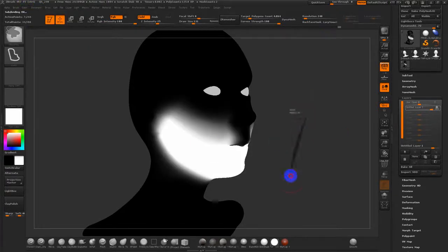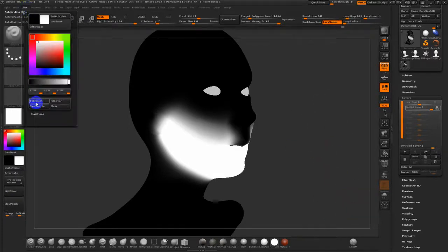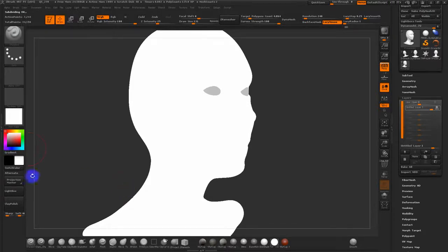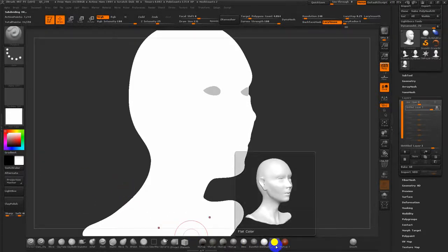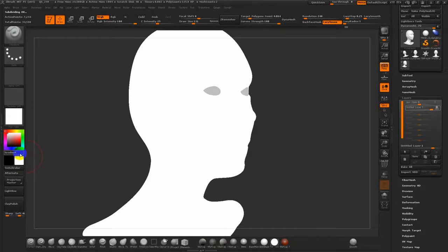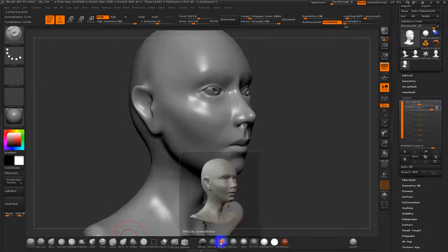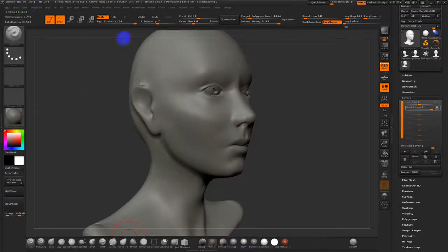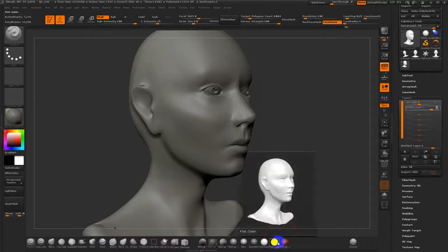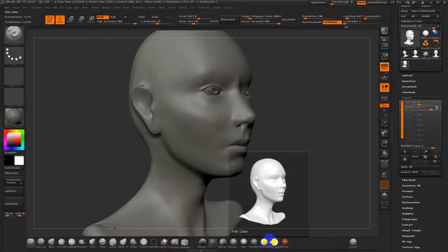Again, I've got to make sure masking is cleared. I think when you start layers with masking involved, it can get kind of bizarre. So I'm going to clear the mask, fill the object. By the way, when you fill a ZBrush model with a flat colored material and a white color, you should then be able to freely jump back to other materials without having to load them through the color palette anymore. But anyways, I have to figure out why ZBrush does this sometimes with layers, where it just fills it with this really horrible black color.